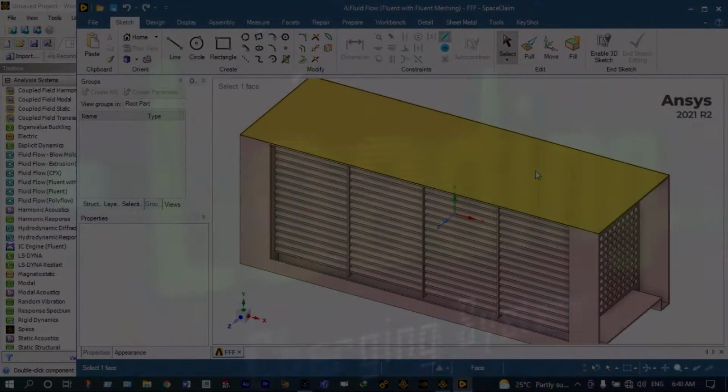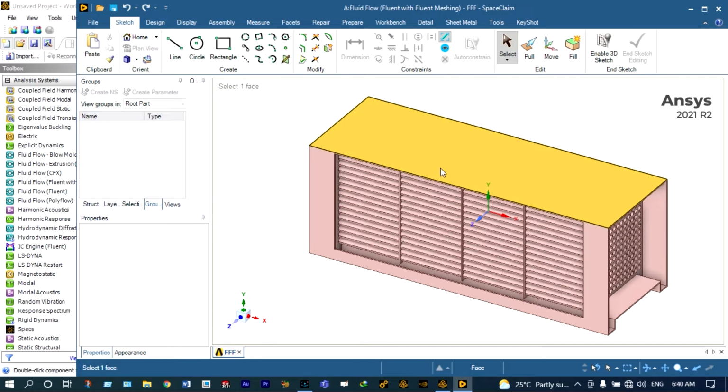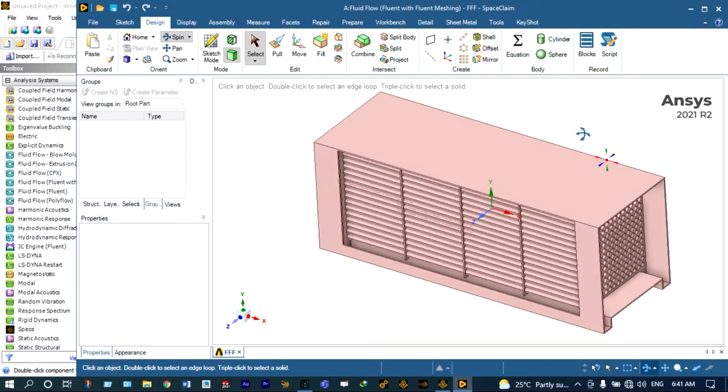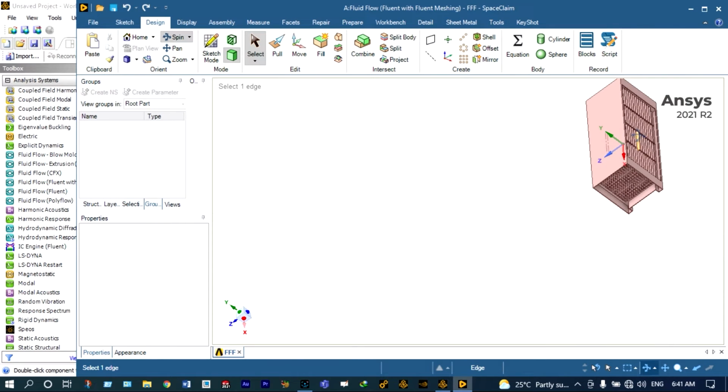Let's get started. Hello viewers, today I'll show CFD heat transfer analysis through a cross-flow heat exchanger using ANSYS Fluent fault-tolerant meshing. This is the model, right? From the left-hand side, we'll be providing cold water, and from this side, we will be providing hot air. And at the exit, we'll be collecting hot water, and at the right-hand side here itself, we'll be collecting hot air, right?